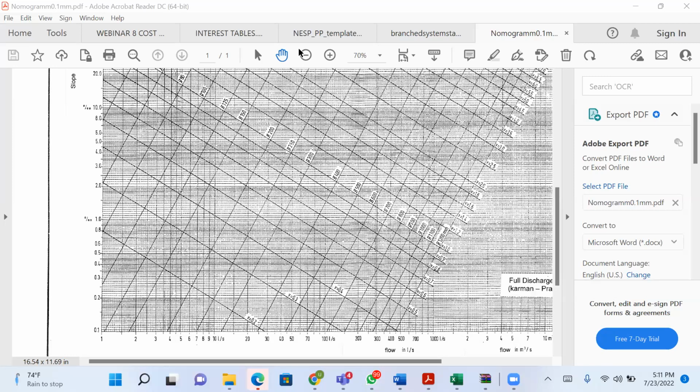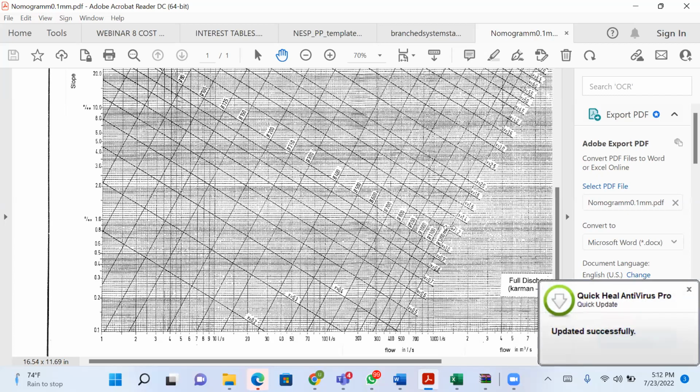Zainab says 600 millimeters. Zainab, check what you've done. That is way too high. Olubenga said 250 millimeter. It sounds more like it. Getting a 600 millimeter pipe in a water reticulation, that means you are designing for the whole country or the whole city. But we are talking about 10,000 population equivalent or 10 streets, okay? Making up of 100 houses per street.